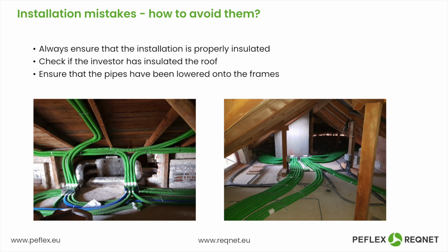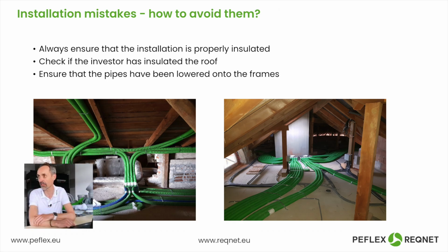Other issues related to poor installation, like pipes nailed or attached to the attic boarding, right? So where's the insulation? It's under the pipes, not above, just under. So again, the pipes are basically in a cold zone, right? So water is going to leak there, 99% for sure.